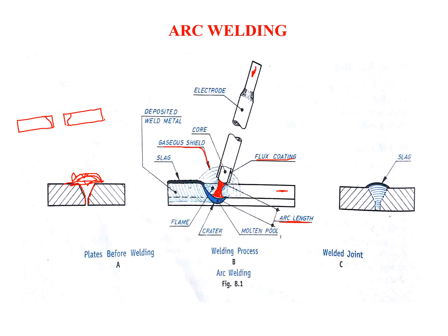the metal piece. This gaseous shield will protect the molten metal from coming in contact with the atmospheric air. If it comes in contact with the atmospheric air, what happens? It will form oxides, and these oxides will weaken the welded material. So here is a molten pool which will not come in contact with air because of the gaseous shield, and the welding starts from this point and continues like this, and these two metal pieces are joined together.